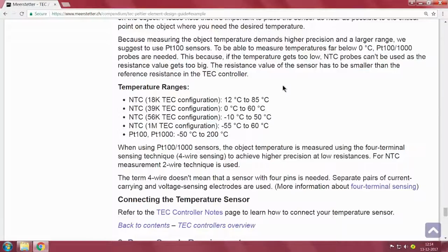So, here one more thing is often we have directly small chips which are taken from any of the standard websites which you can continue to use, but by definition invariably we are expected to use 4 wire sensing because we are dealing with thermal parameters, and all wires also have a temperature coefficient, and we are talking about small changes 0.1, 0.2 millivolts change.